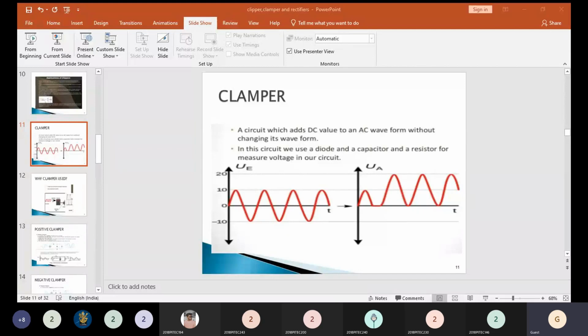That's why practically in many places they use a normal type of transformer. So in the center tap transformer, what happens? The same concept with diodes D1 and D2. In the positive half cycle diode D1 will be on, and in the negative half cycle D2 will be on. So this is the value of the DC signal. In an analog circuit, the AC signal supply you give at the input side, and you get a DC signal.